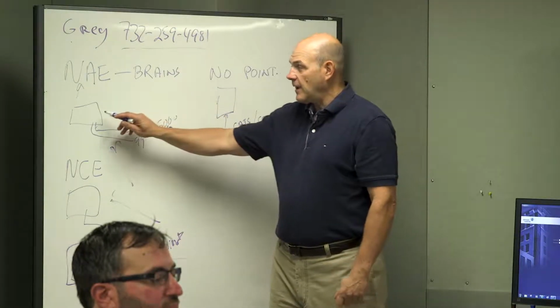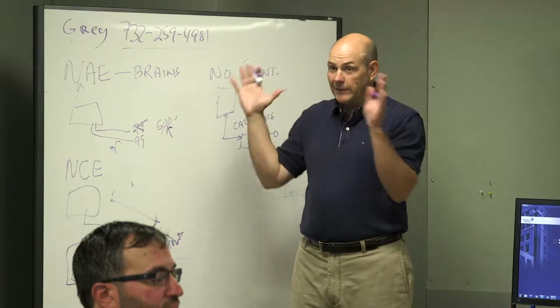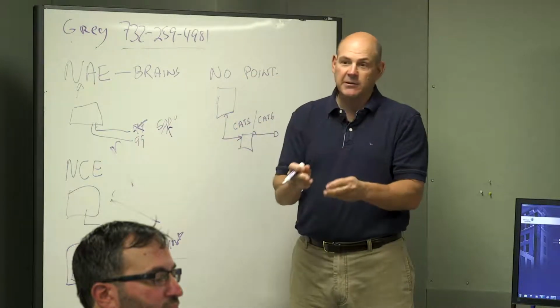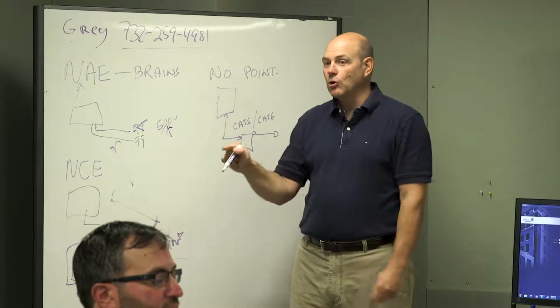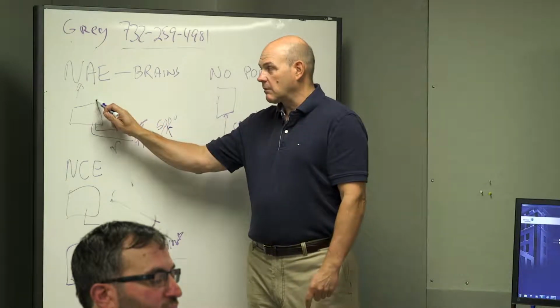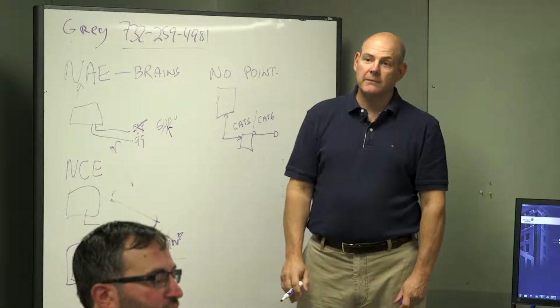So if this NAE is controlling the cooling tower, everything is going to be blank. The VFDs, the temperature sensors, everything is going to be blank. So don't look at the individual controllers downstream. You're going to look at the big guy, right?